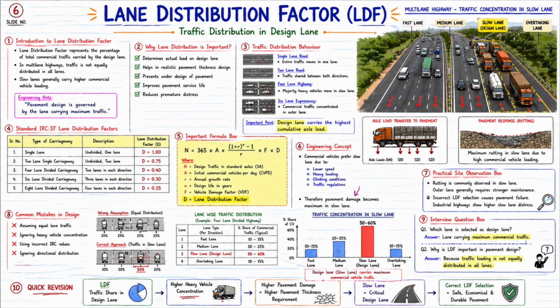Nine: interview question box. Q1. Which lane is selected as design lane? Answer: the lane carrying maximum commercial traffic. Q2. Why is LDF important in pavement design? Answer: because traffic loading is not equally distributed in all lanes.